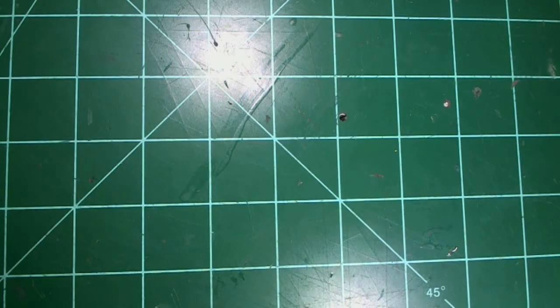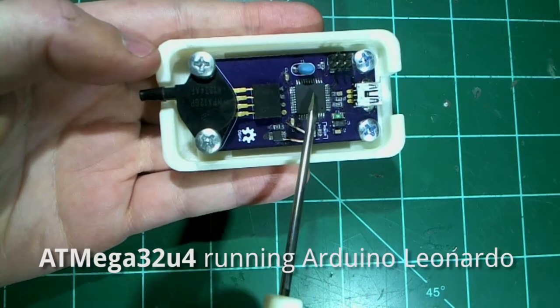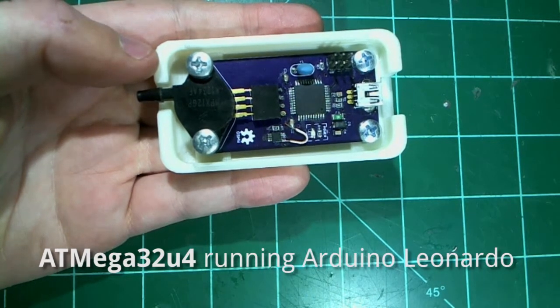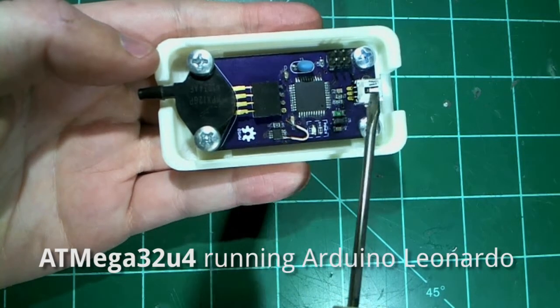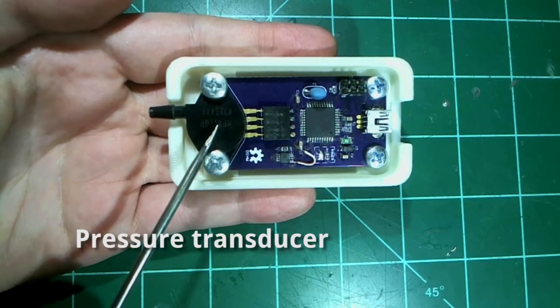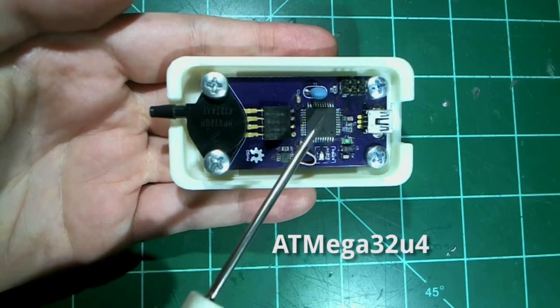So let's talk about hardware. At the heart of the openSip+Puff is an Atmega32U4 with the Arduino Leonardo bootloader flashed onto it. This is what allows the board to connect to your computer as a USB HID device via the USB Mini B connector. An MPX12GP pressure transducer is connected to an instrumentation amplifier, which in turn is connected to the Atmega32U4 on an analog input pin,